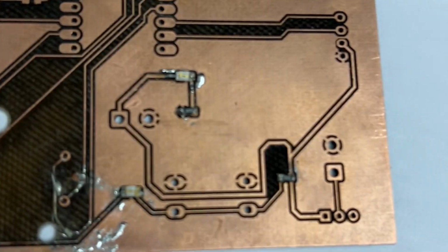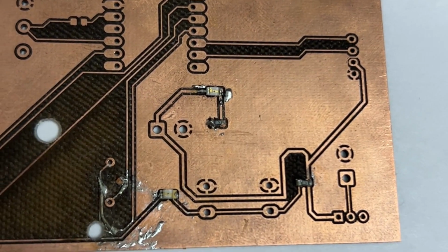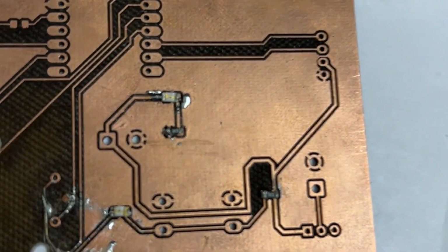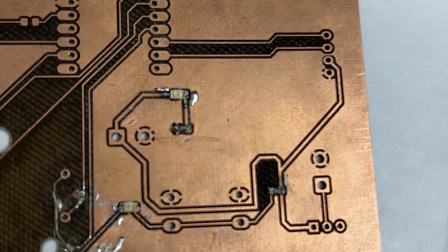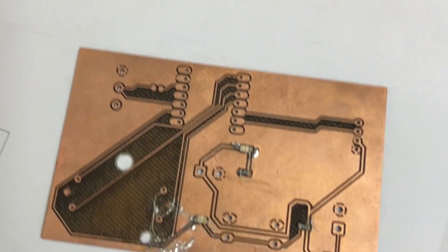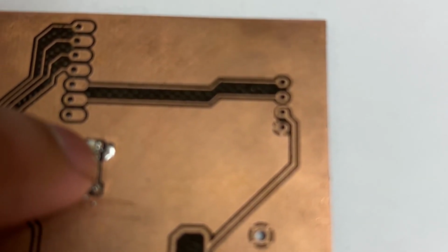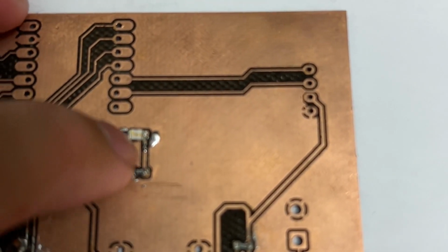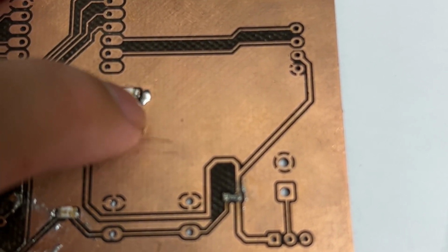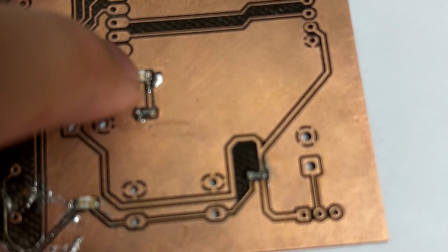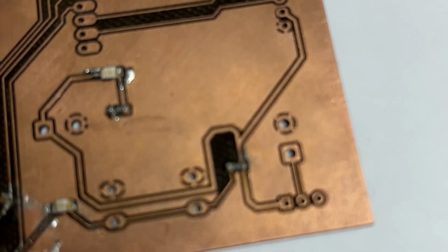Okay, so this is definitely something you want to avoid when you want to do hand soldering. If you are using heat guns or any kind of soldering masks, this is definitely avoidable. And in the meantime, you don't want these right angles to occur on your PCB board, because if you are soldering it like this, that solder is super difficult to attach to your track without touching the ground plane.